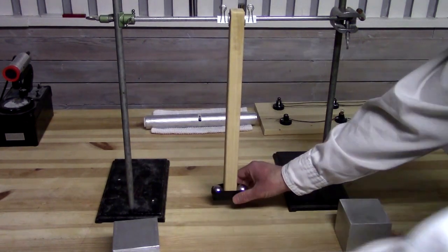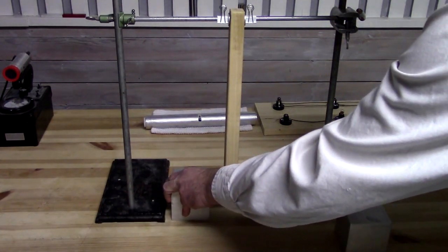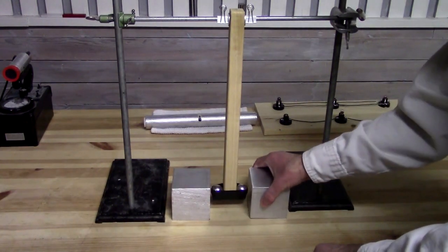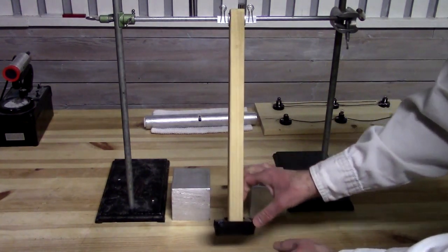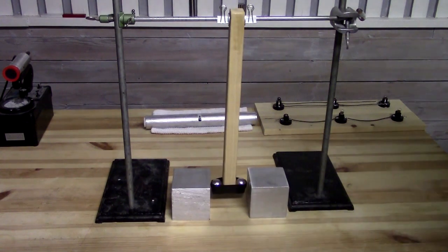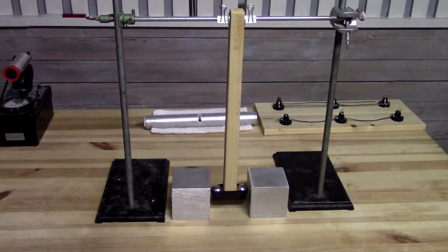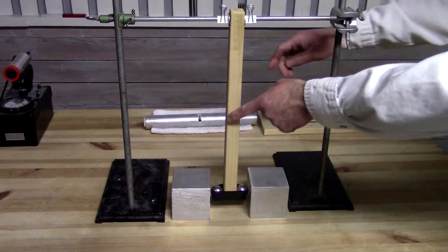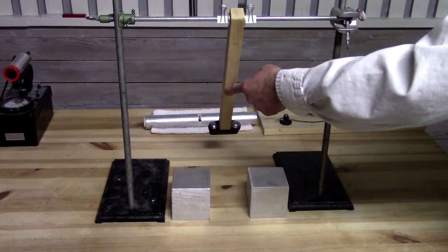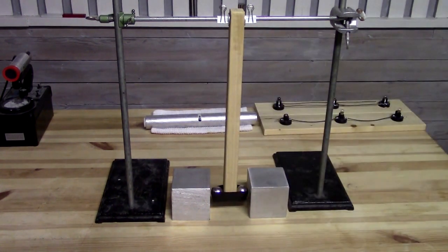But as soon as you have those blocks of aluminum there, you're going to have current being generated through the generator effect, and that current produces a force between the conductor and the magnet, and in this case that means the magnet's motion is opposed. And it doesn't matter which way the magnet is moving. If I drop it from back here, it still comes to a fairly rapid stop.